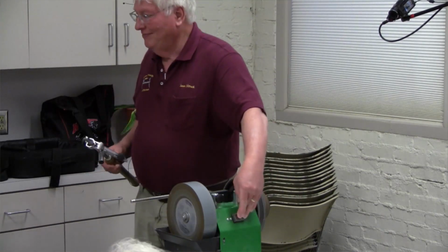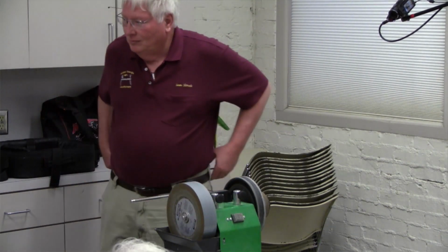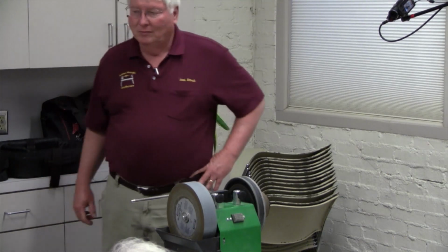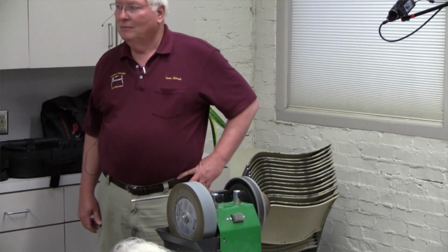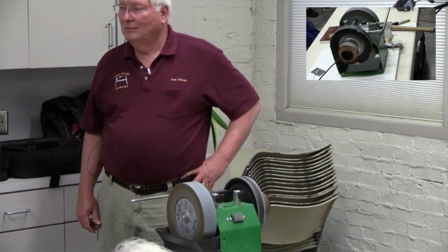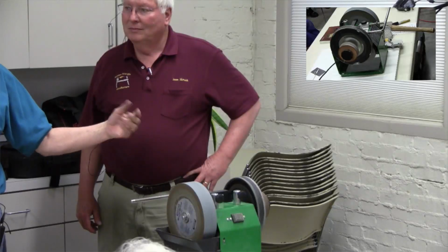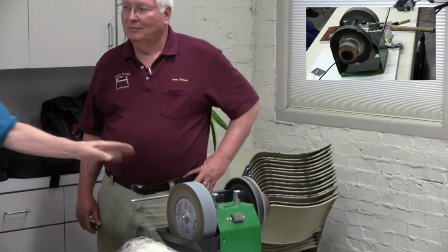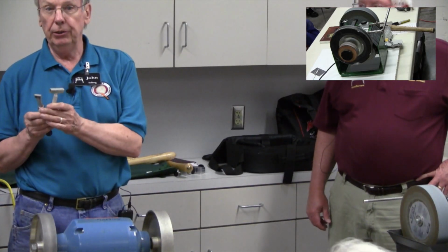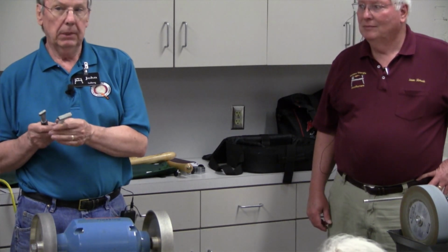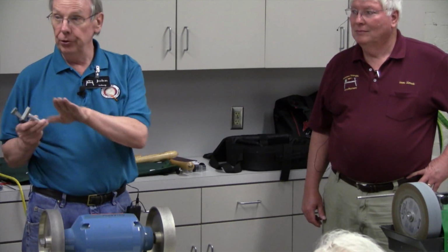Sam just brought up a really good point. If you use an aluminum oxide wheel on one of these grinders, you want to make sure that it's flat and it's clean. So you've got to have a diamond dresser to dress that wheel periodically. He has the same problem with this wheel. He's going to have to dress it periodically if he ends up grinding only in one spot. So with aluminum oxide wheels, you've got to make sure they stay sharp, and they stay sharp by dressing them, cleaning out the old particles of steel that get embedded in them, and making sure that they're flat all the time.